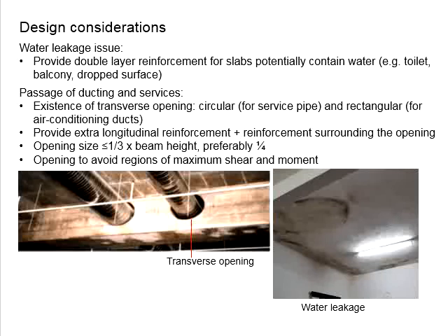You have to be careful with your design also, which, if you observe from the architectural drawing, normally they give you the intended flow of the water from the basin, from the toilet, from the floor trap towards the drainage or towards the septic tank. Typically, ceilings are given a height of about 600 mm. If you use up the full 600 mm as the beam height, that means you are blocking the pathway of the ducting and services, especially when you talk about the first floor plans.